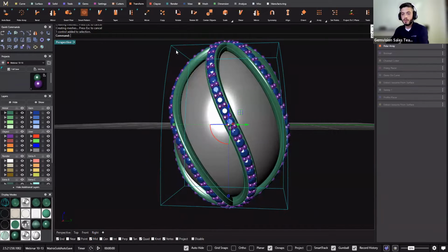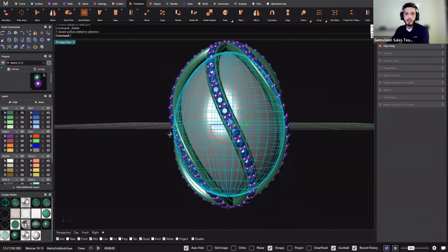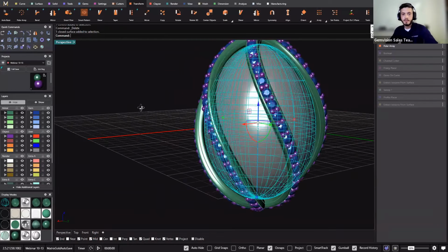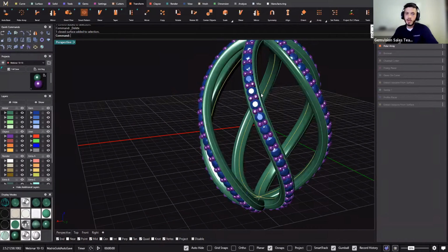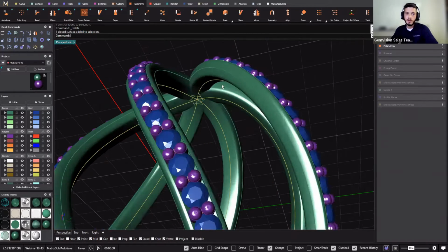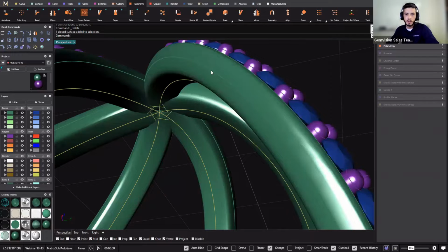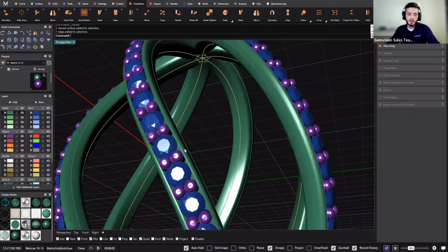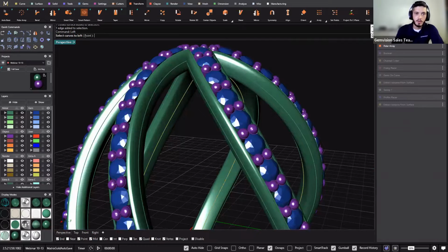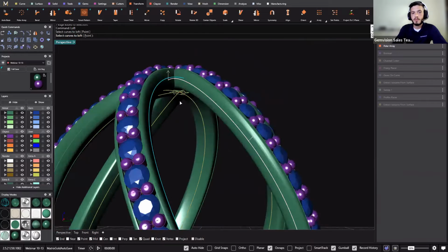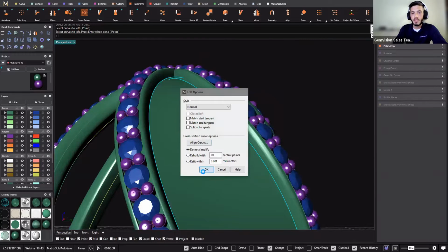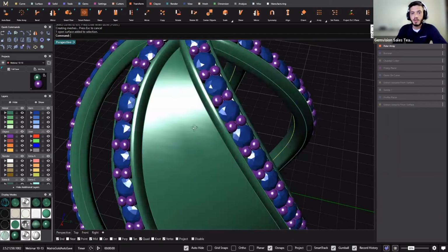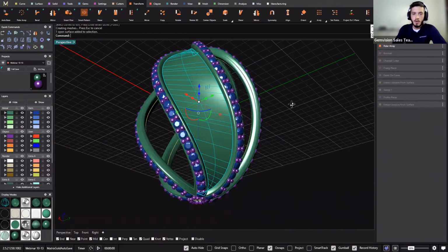Okay, so one more step we can add to this now that we have our egg, right? Is I have these seams right here. If I can get them, right? That we can loft, right? So loft is a basic Rhino command. I think they might be overlapping, but let's see what our surface looks like. Yeah, that's not too bad.